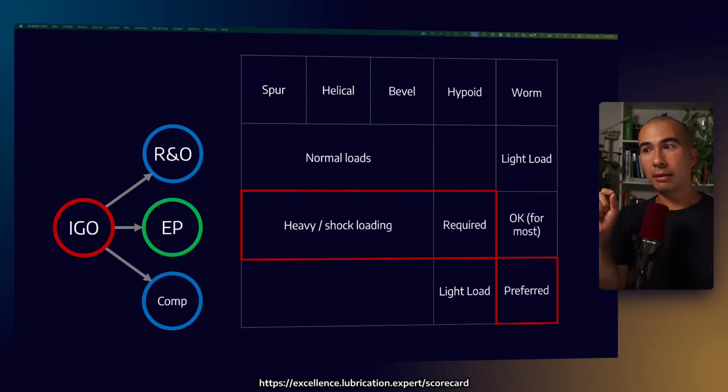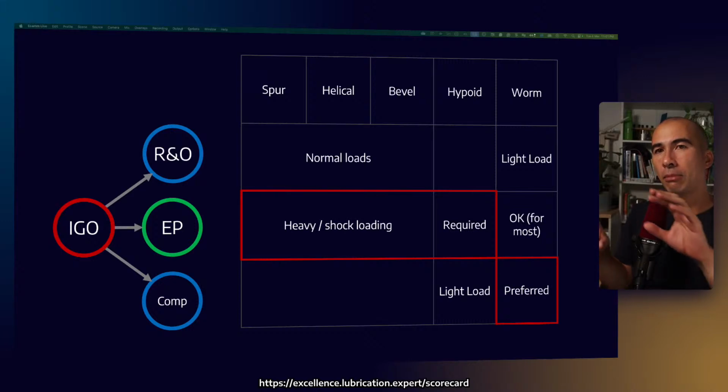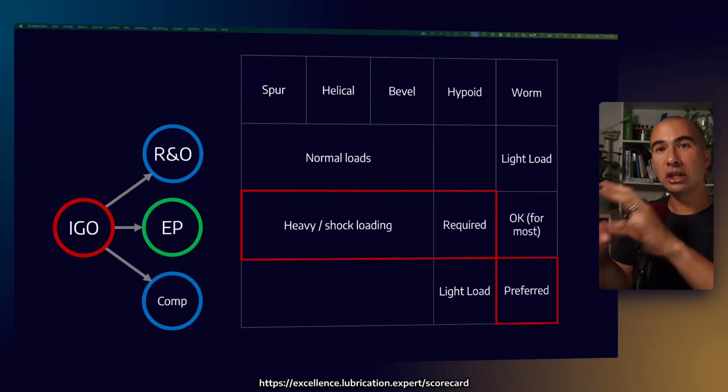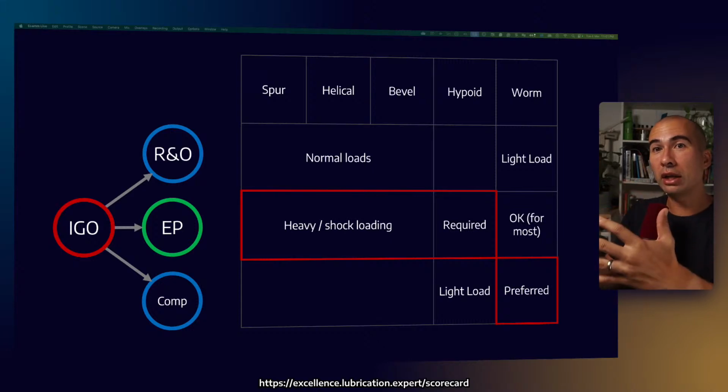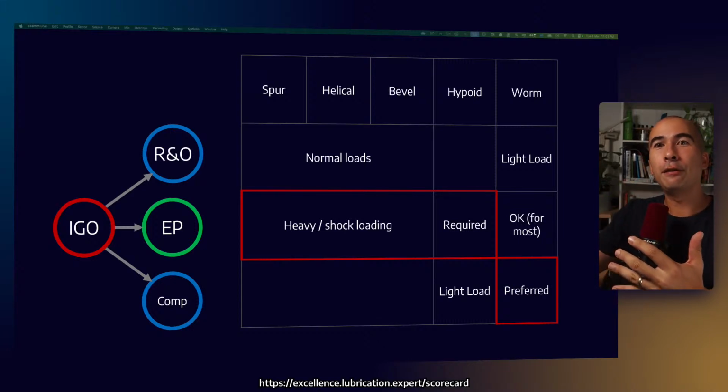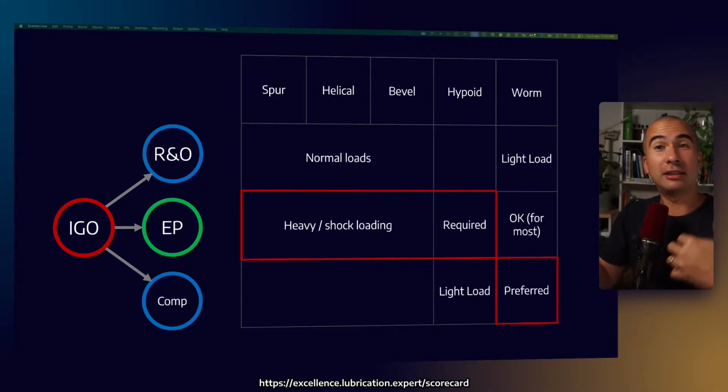In fact, that's one of the big splits between mobile hydraulic equipment and industrial hydraulic equipment, which we'll get to in a second. Mobile hydraulics, traditionally, have used something called a cutback engine oil, which is basically you took an engine oil, deleted out 50% of the additive package, and said, well, that's good to use as a hydraulic oil now. Okay, so hopefully that answered the question. All right, so let's go on.